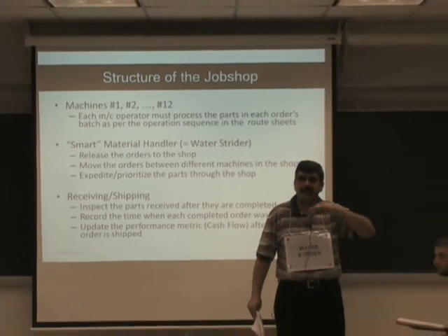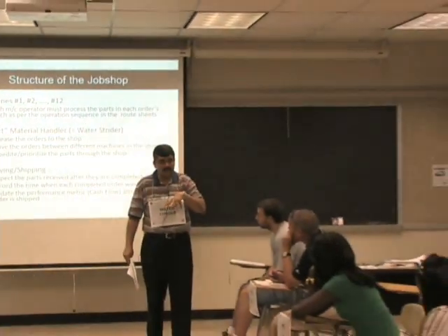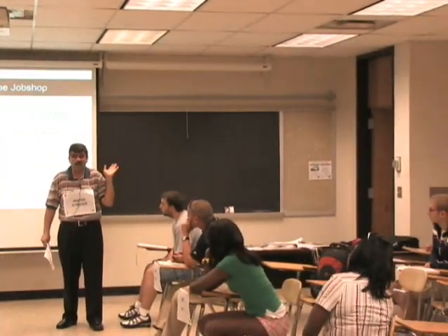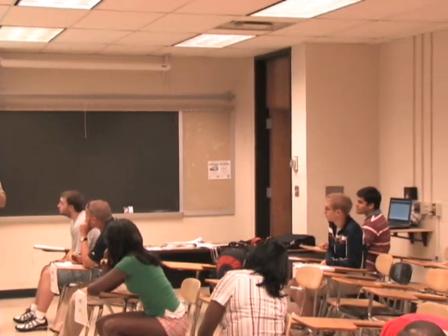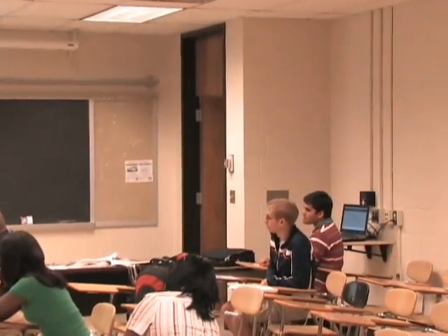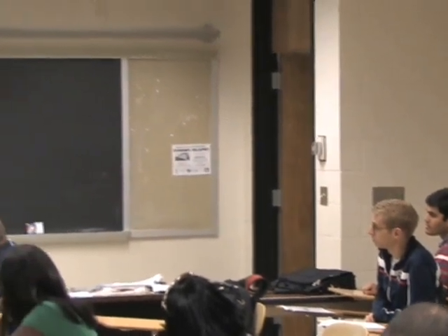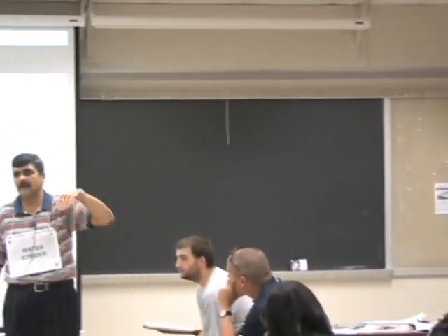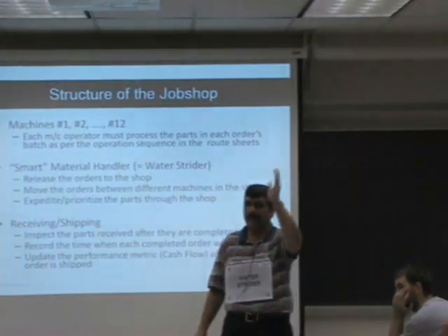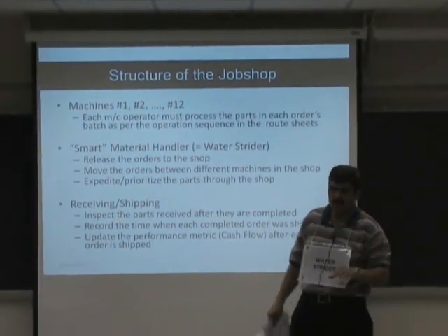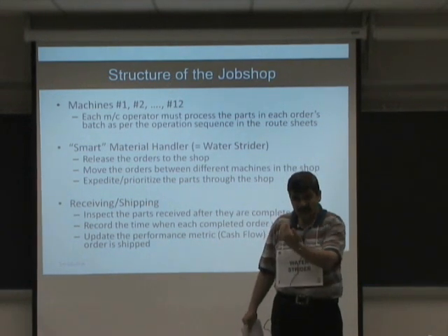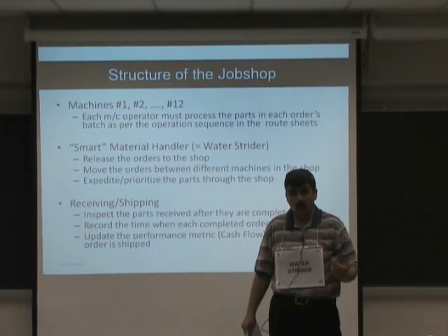Okay, the point again is that I am not focusing on quality during this game. Why? Because quality is number 1. You cannot pass on bad work to the next operation, period, okay? And that's why what people do is they train employees to inspect their own work, to be responsible, and not have inspection as a separate department in the facility. That is reserved typically for government mandated, or customer mandated inspection. It has to be done, and you typically require expensive equipment kept in one area. Okay, in those cases you send work for inspection to those areas. Otherwise, decentralize, put inspection at source, where the work is done.